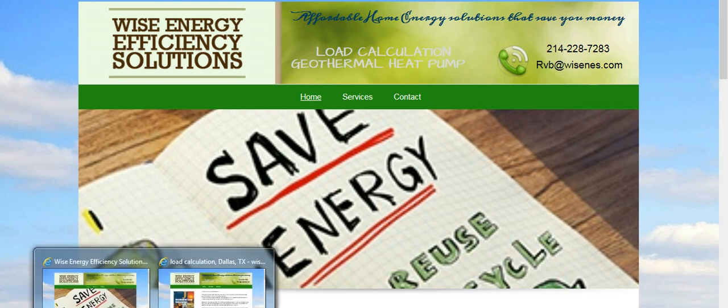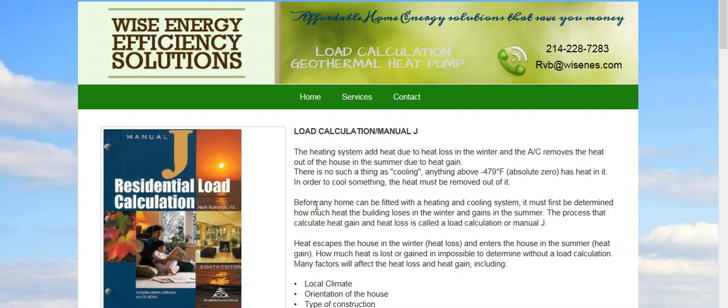So first, what is a load calculation? Well, before any home can be fitted with a heating and cooling system, it must first be determined how much heat the building loses in the winter and gains in the summer. The process that calculates heat gain and heat loss is called a load calculation or a Manual J. It's the same thing. The load calculation calculates the heat gain and heat loss in BTU.